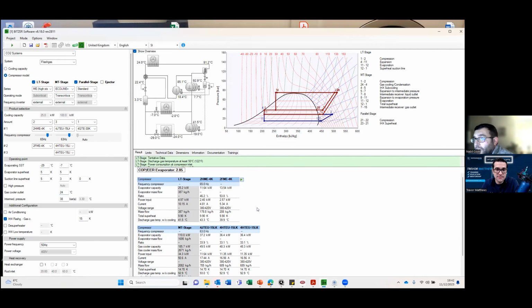Well, this is really what tells you not what the peak effect of your parallel compression is, but what your annual average effect of your parallel compression is. And that's what matters to the bill payer. That's what matters with your business case in terms of return on investment. So we may have seen 1.51 to 1.86 in COP, but what really matters is the net impact.